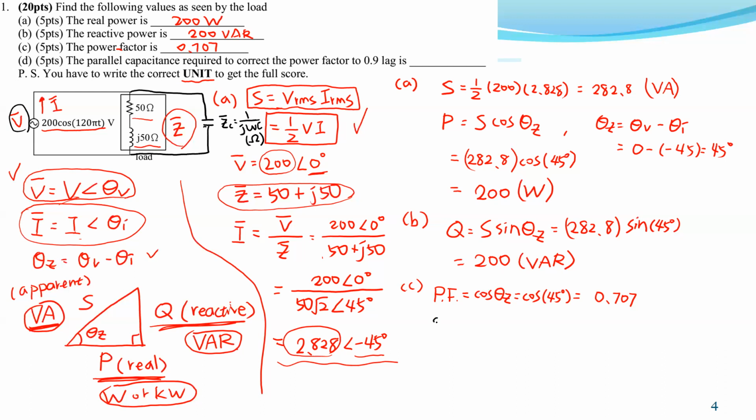So the complex power S equals 1 over 2 V squared divided by R plus J 1 over 2 V squared divided by X. We have this complex power equation when two components are in parallel.